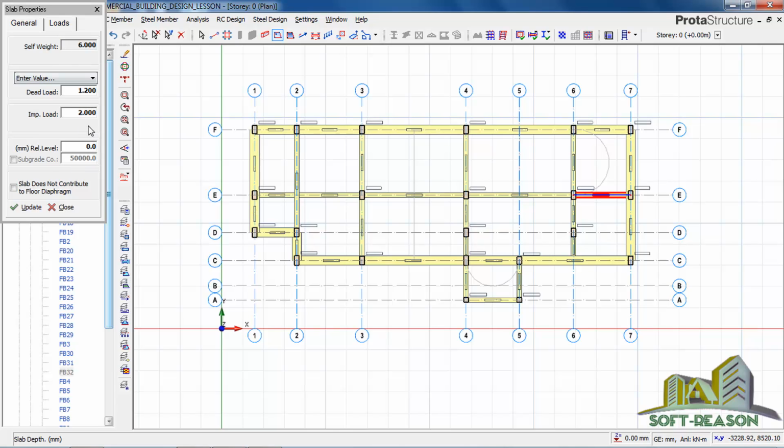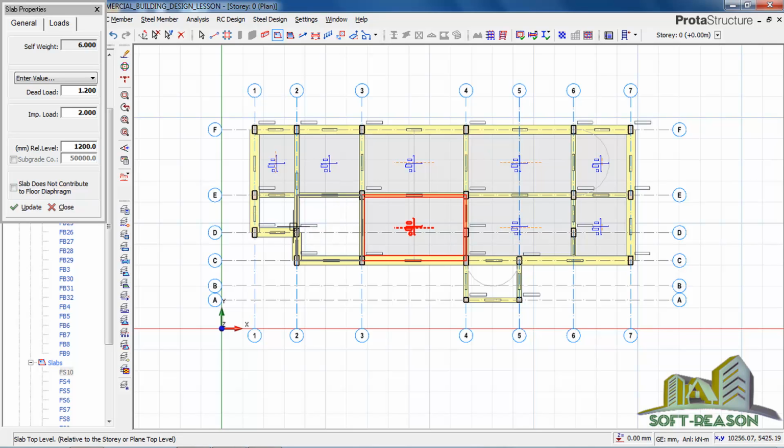So you come to loads, this reference level. You are going to minus 1.5 minus 250 minus 50. If you do that, you'll be having 1.5 minus 300, so you will be having 1200. That is to say, the height of the slabs from the ground level to the top of the beam is 1200. So we will extract the slabs. This is the foundation slab for the raft.